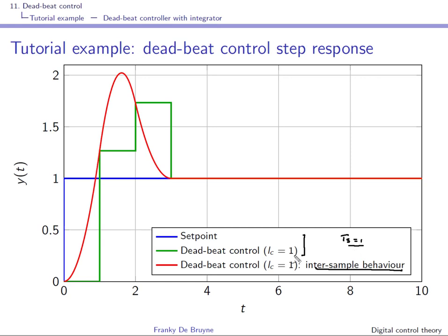You can see that the presence of this additional integrator in the controller, that is not necessary to follow a step response, but that we have introduced here to follow a ramp response, or to be able to reject a step-like load disturbance, has had consequences on the closed loop step response, because it has become a lot more problematic in the sense that the overshoot is very large.